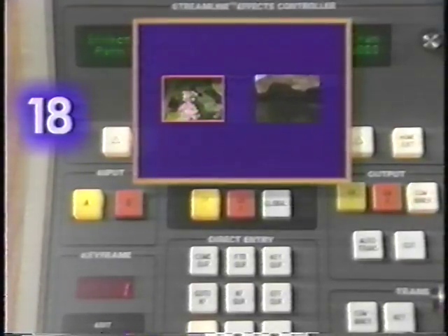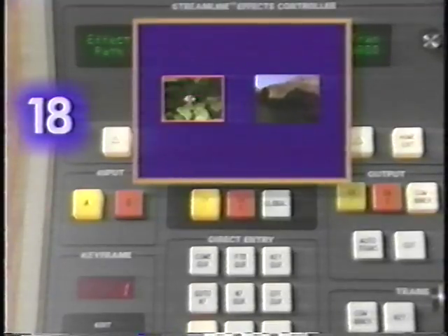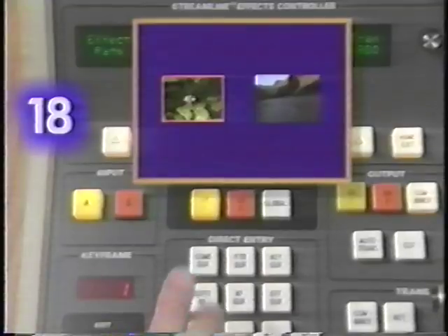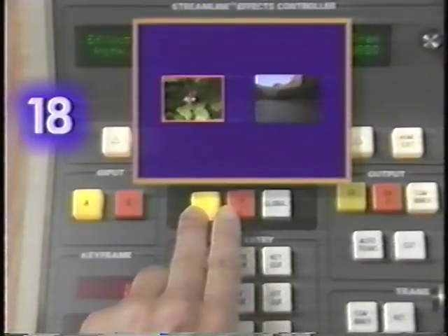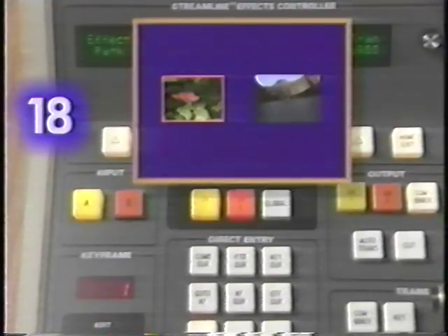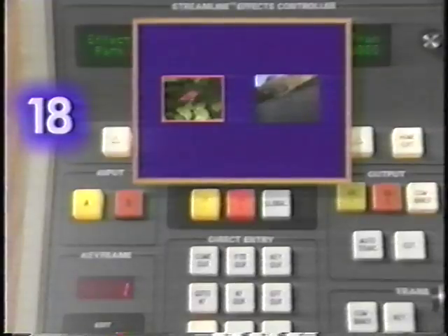A Modify path will be affected by any changes made in the active path. Its status will not be shown in the keyframe display or by the push buttons. Select paths for modifying by holding down the Active Path push button and pressing the desired Modify Path push buttons in the Delegation section. If a path is not selected for an active or modify state, it will not be affected by any changes made in the active path. Its status will not be shown in the keyframe display or by the push buttons.